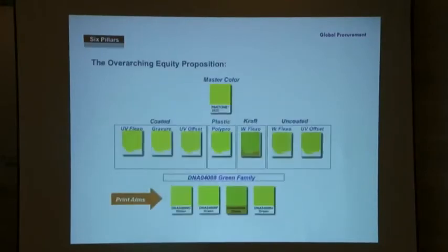When I do the brand standard development, whoever built the master program gives me a Pantone value. If I took that and printed across all these different types, I'd have a mess. So we develop these, we give them to the ink manufacturers, and they give us what we want. As a printer, my job's real easy. This ink has been aligned for my analogs, my volume, my plates, my cylinders. They have to be the partner in this, but if you just tell them the lab values, they really can't give you what they need.